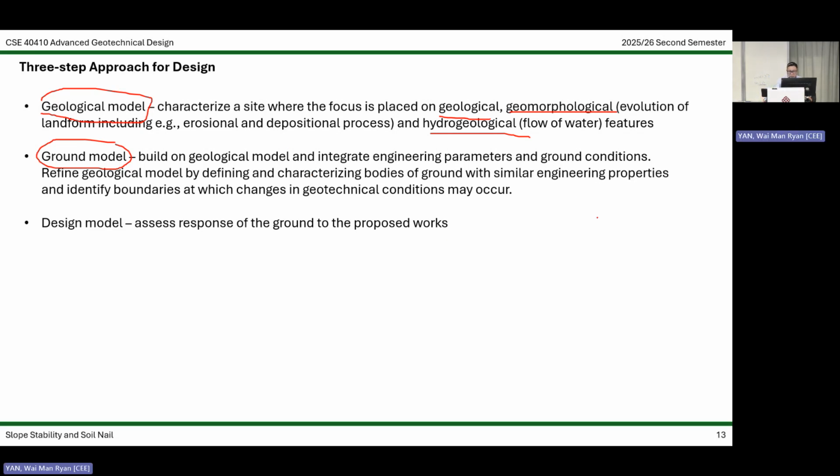For instance, if I have a log that contains lots of GI information, you may have a layer of fill, and then you may have some decomposed granite, but maybe some grade 4, grade 5, grade 4, grade 5 sandwich. And then later, you have grade 4, grade 3 rock like this.